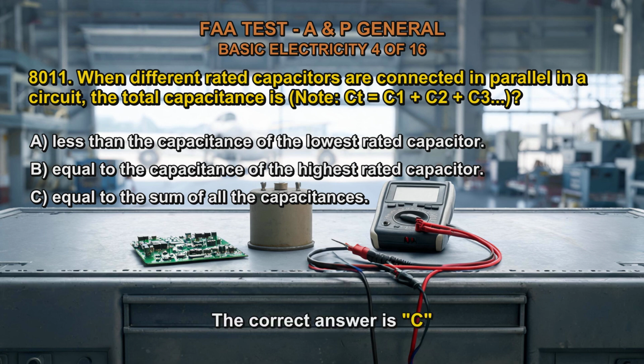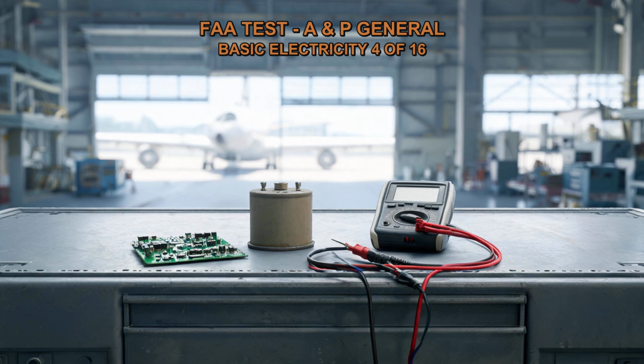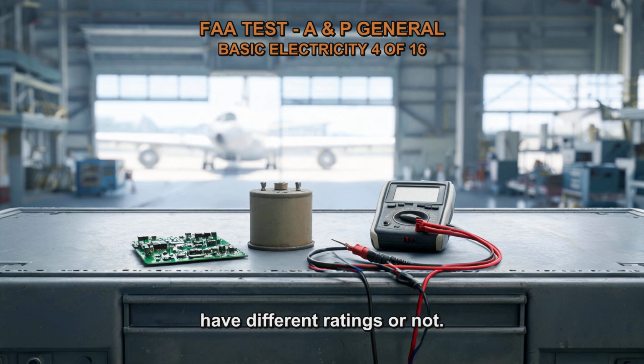The correct answer is C. When capacitors are connected in parallel in a circuit, their capacitances add up to give the total capacitance of the circuit. This is true regardless of whether the capacitors have different ratings or not. Therefore, the total capacitance of the circuit is equal to the sum of all the individual capacitances.